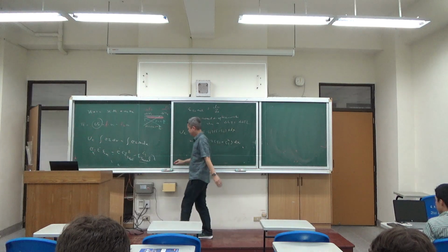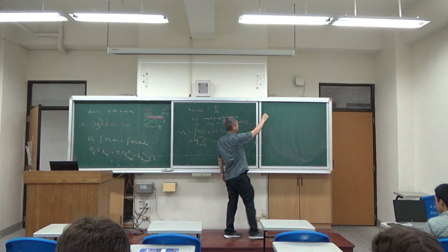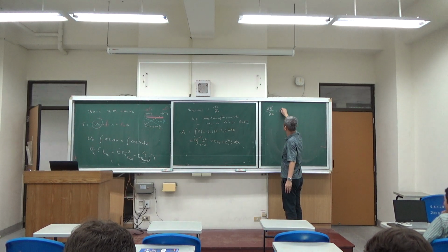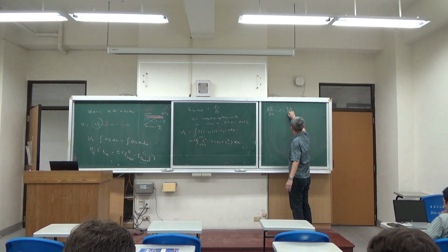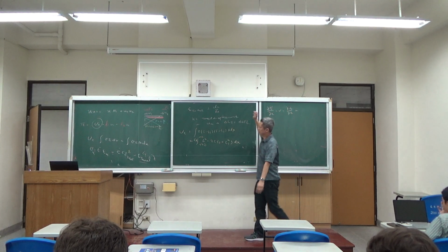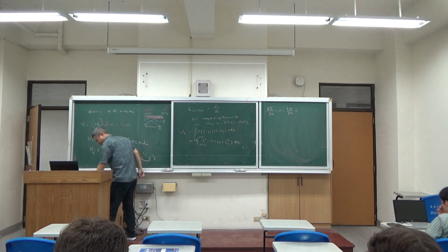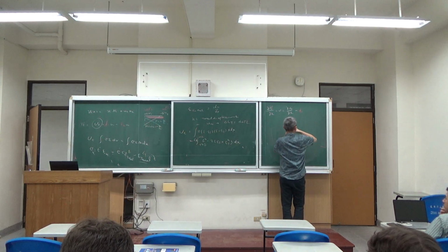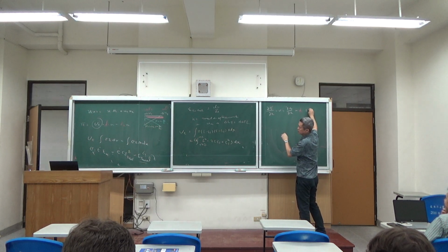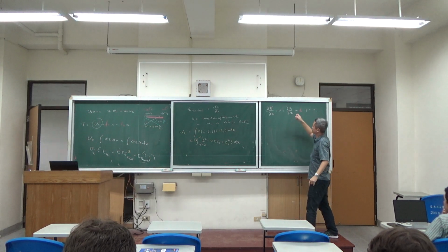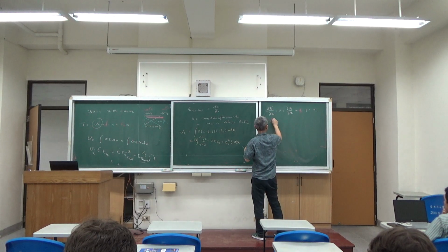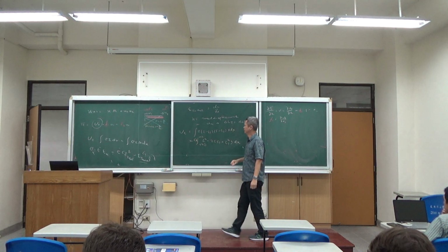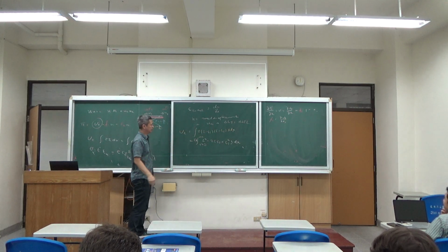To find the force balance, you have the partial differentiation of the total potential energy with u1, minus the force, which is F1 times 1, and the other terms are 0. So this is the way you find the force expression. F1 is equal to del U_E over del u1. Let's see how you can obtain this.